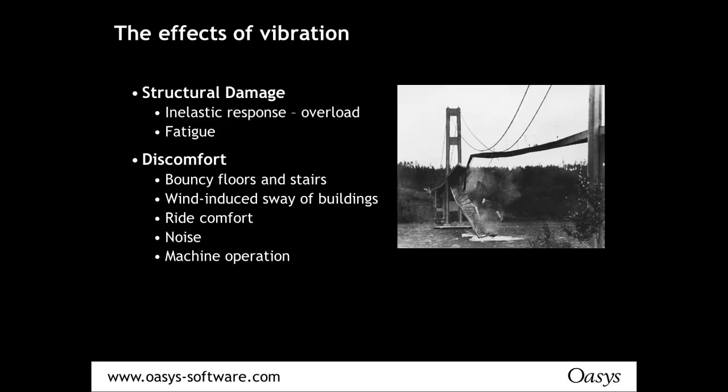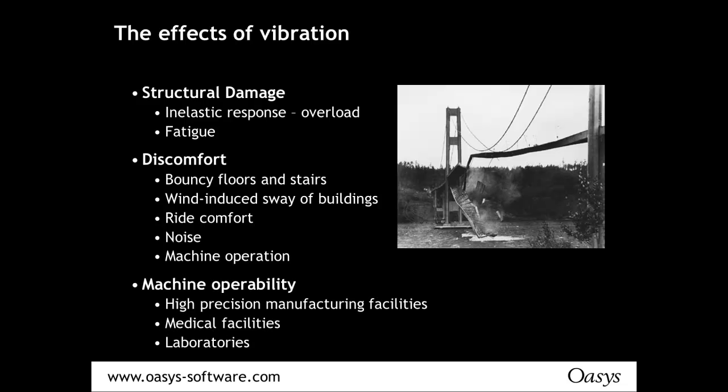Then there's the whole serviceability side, which is to do with discomfort and so on. And then there's another serviceability aspect of doing machine operation. So microscopes, both optical and electronic, medical facilities, laboratories, and so on. Things which require careful control of vibration.